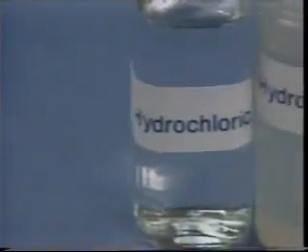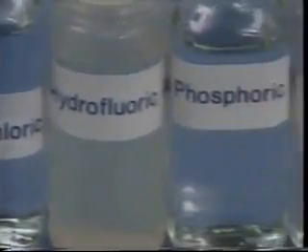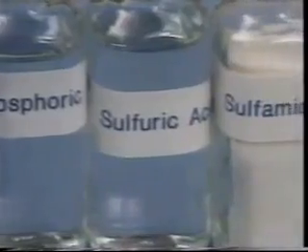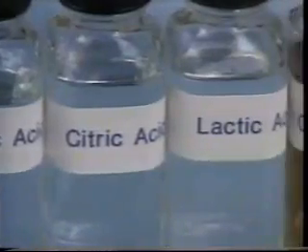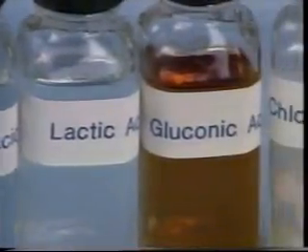The inorganic acids, like hydrochloric, hydrofluoric, and fluoboric, are considered strong acids because of their ability to dissolve a relatively large volume of solids with a small volume of liquid. On the other hand, organic acids, any acid containing carbon, are generally considered weak acids. Their main advantage is that they are less corrosive to metals than HCl or HF acid.